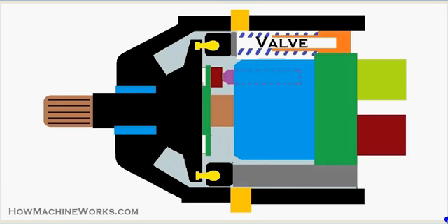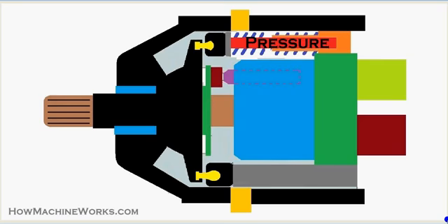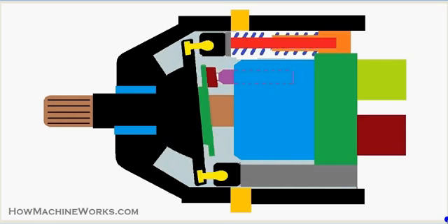So when the valve gets pressurized, the pressure is getting into the valve, resulting in the swash plate angle changing. So you can see when the swash plate angle changes, the piston is actually moving back. You can see the movement of the piston back, which results in a suction. At the top, the piston moves back, and at the bottom, you can see the swash plate is moving towards the front. So that's the change in angle of the swash plate over there.